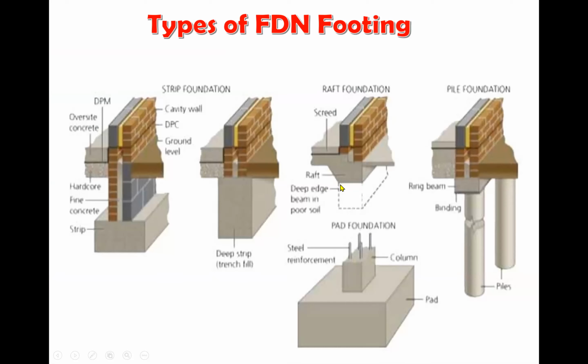The reason why I discussed the wide strip before is because I want to show you that if you have wide strip and your walls are very close together, you're going to realize that the foundations may start overlapping. So the recommendation would be using your raft foundation where it covers the entire area, and you don't have to create a floor, because it's like a slab on top of the ground, and then underneath the walls you'll have the foundation going down like this. So your raft foundation is like wide strip combined going across, right? So you could use that.